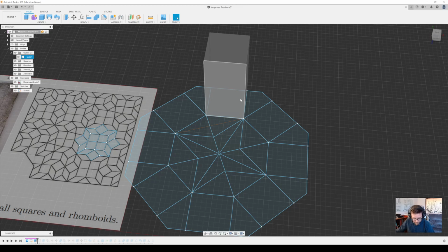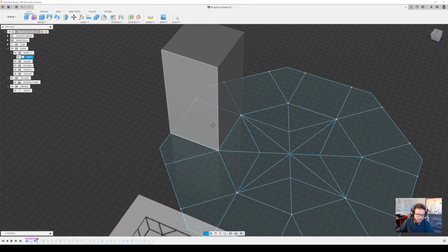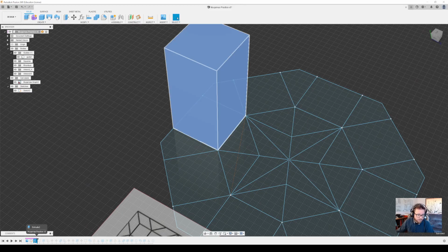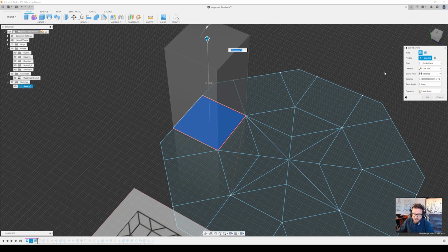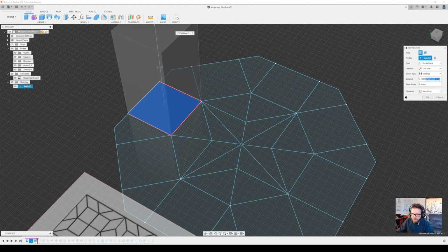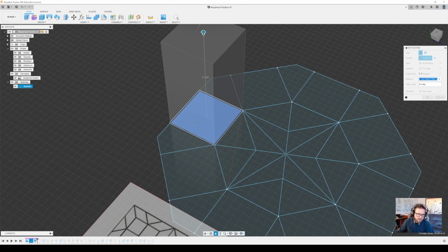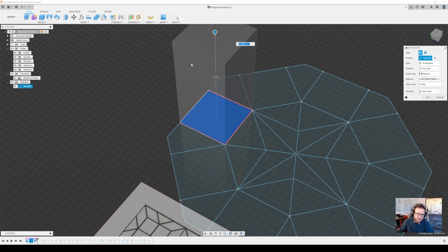What I did, which I think is pretty simple, generally to get my height for the Muqarnas vault itself, the individual tiers. If we right click and say edit feature, you can see that I multiplied the width. This is the width of the square, and I just multiplied it by 2, so that this is a 2 by 1 relationship between the footprint and its elevation.